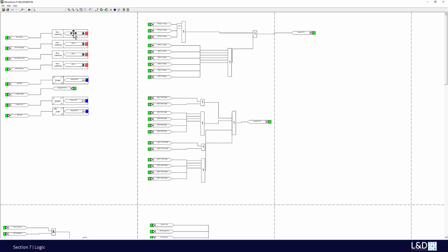And for example, LED 5 to 8 will use one of these reserved virtual outputs. So that's just a brief introduction of the virtual outputs, and we'll get a more detailed introduction of the flex operand, the PSL editor, and how to use these virtual outputs in another training module, 106.